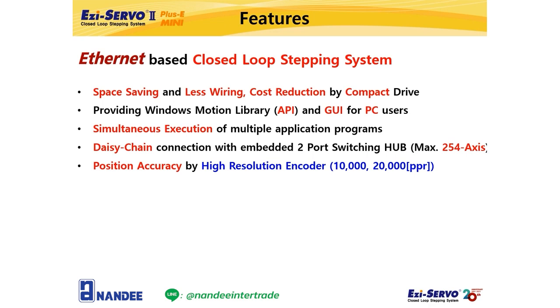Due to the characteristic of the stepping motor, it does not require separate gain tuning, which can reduce maintenance effort. For example, you can just power on the motor and operate it without gain tuning. Since the holding torque is large, there is no vibration after stopping compared to the servo.